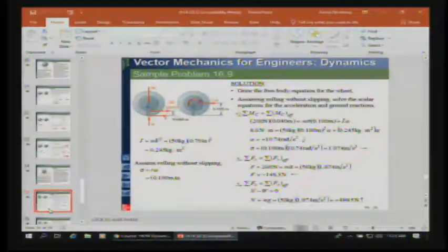All right, so if we draw the free body diagrams, once again, we have to remember the weight. We have a force from the cord. We have a force from friction. We have a normal force. And we have the inertia vector, and we have I alpha. So this is actually a really good drawing to start out any sort of rotating problem, to think about the forces equals the mass center acceleration, or the inertia vector, and the rotational piece.